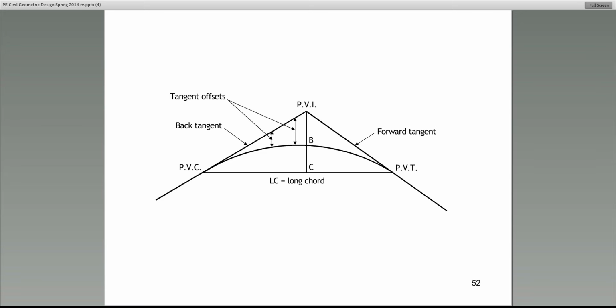The whole purpose of a vertical curve is to recognize what the contour of the road or the natural elevation of the various points along the curve is, and in order to get the actual parabolic curve, we need to identify at each given station how much cut or how much fill we need to have, all right?